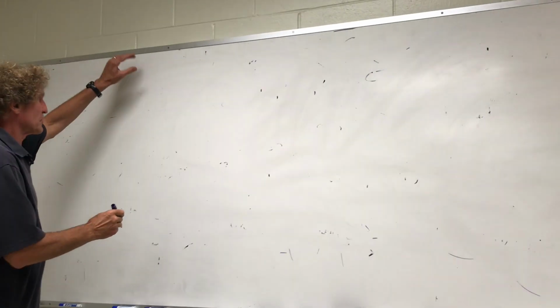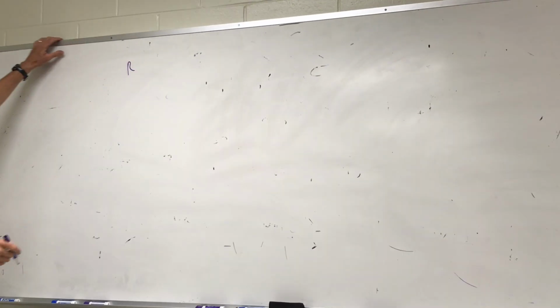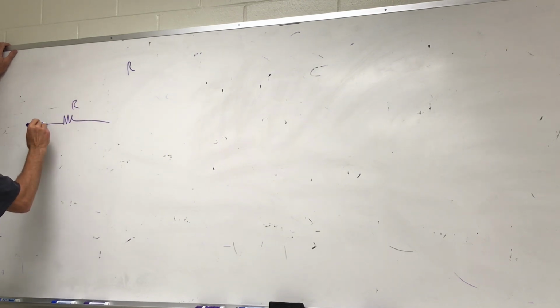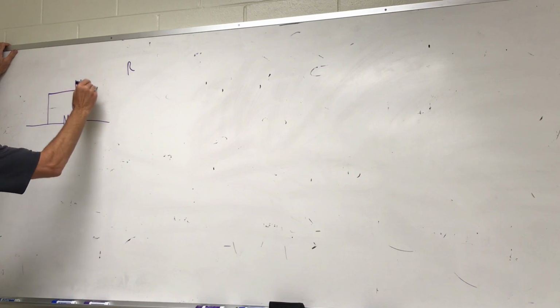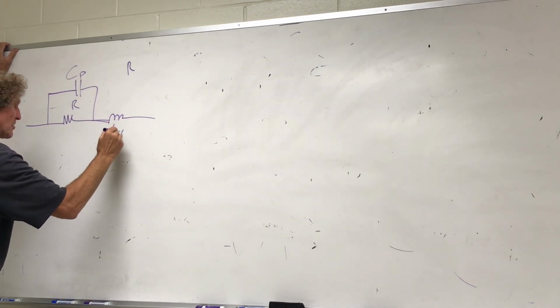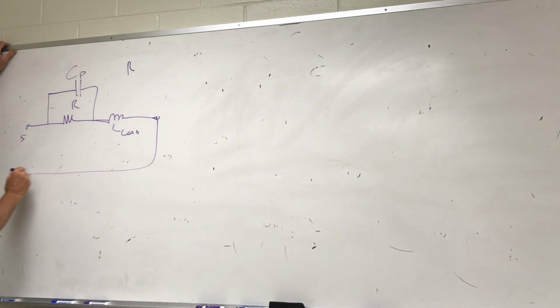So what might be on the quiz? Why don't we talk about a resistor? Remember what a resistor looks like? That looks like a resistor for starters. Then it has ye old capacitance that's a parasite. And then it has an inductor here, and it's called the lead inductance. What you really want is the impedance between these 2 points. So you'd like to know what Z is here.